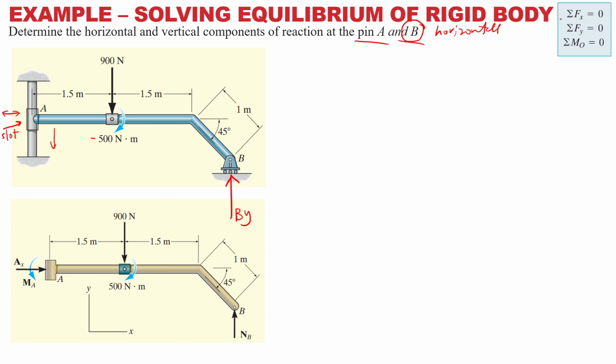So this is how your free body diagram should look. Again, start with summation Fx, then summation Fy, and finally do your summation of moments. Okay, so let's not be lazy, right? Let's do this. Summation Fx is equal to 0. Look at this. You have only one component in x. Is there anything else? No. Only AX. AX is positive, because it is assumed to the right. You can assume left too actually. There is no vertical component. Where is the vertical component? This question needs to be changed a bit. It's trying to confuse you. It only has horizontal.